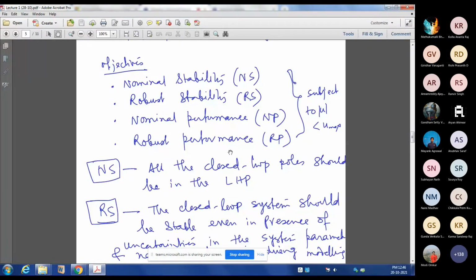For a stable system, feedback is only needed in order to have disturbance attenuation, because response characteristics you can easily shape using a pre-filter. But disturbance you cannot attenuate using a pre-filter. You have to have feedback, otherwise disturbance cannot get attenuated.